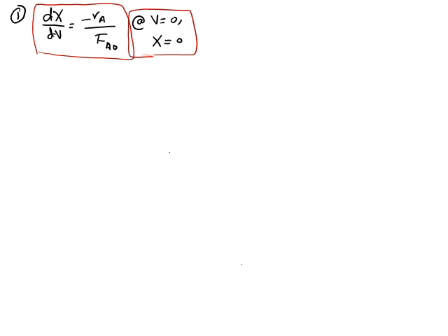Step number 2. What variable did I introduce here? It is the minus Ra. That's a variable that I introduced and we need to provide an equation for. Which takes us to step number 2, writing the rate law. It says first order with respect to acetone, so k times Ca. Very good, we wrote the rate law. What variables do we have? We have k and Ca. Ca we will take care of in the stoichiometry. k we need to take care of now, so let's write an equation for k.